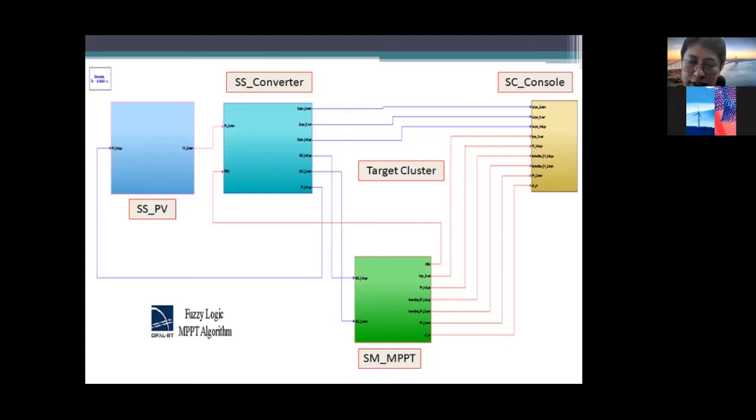Here we have a master. The master is the MPPT, and the slave in this case is the solar PV. You develop a PV model in your design and your DC boost converter. Then this particular console will measure the different parameters of your design, such as power, output voltage, or even output current, and you also measure the response of the PWM duty cycle during operations.